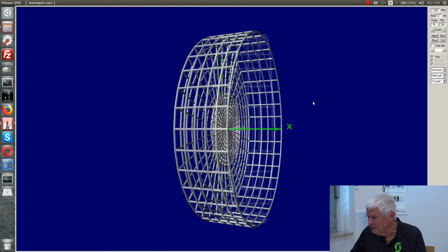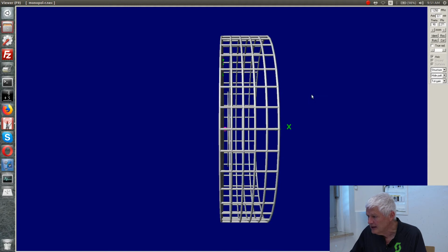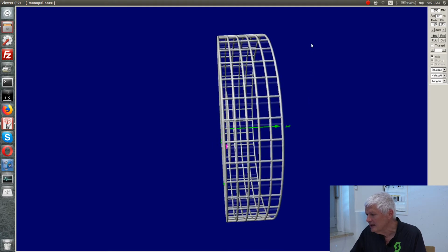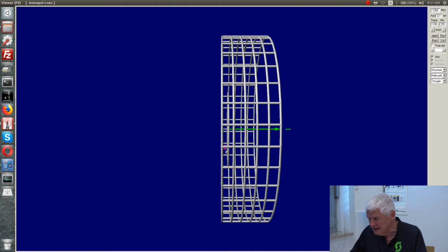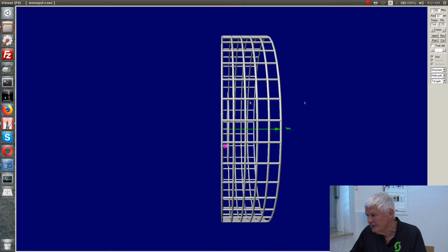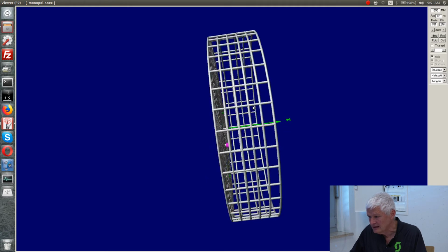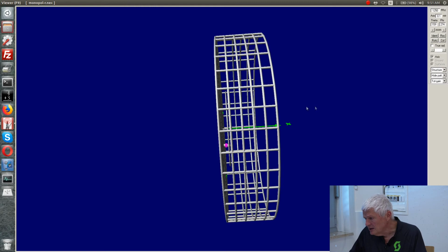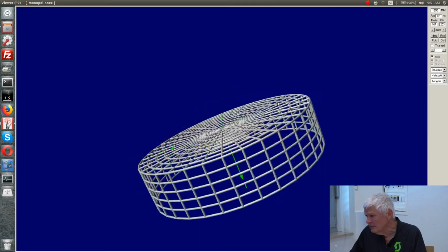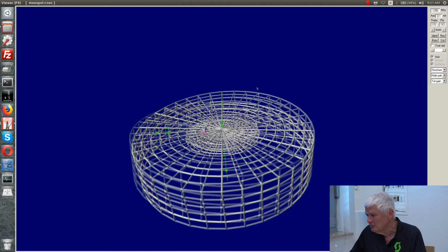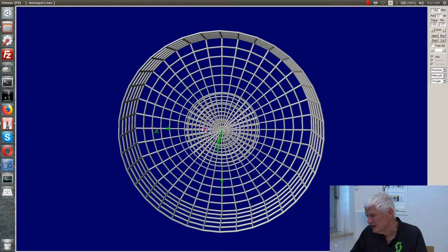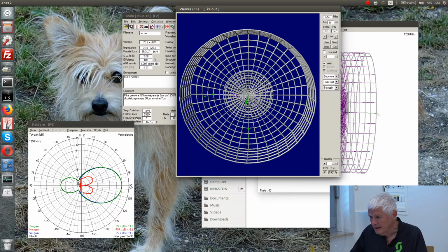If we look at it from the side, you see where the generator is located. The generator is located between the patch, eccentrically, of course, to excite the suitable mode in the microstrip patch. And the microstrip patch has an air dielectric here. This is quite a useful antenna with around 11 dB of gain. Here is the generator. The generator, you see, has a nice pattern.